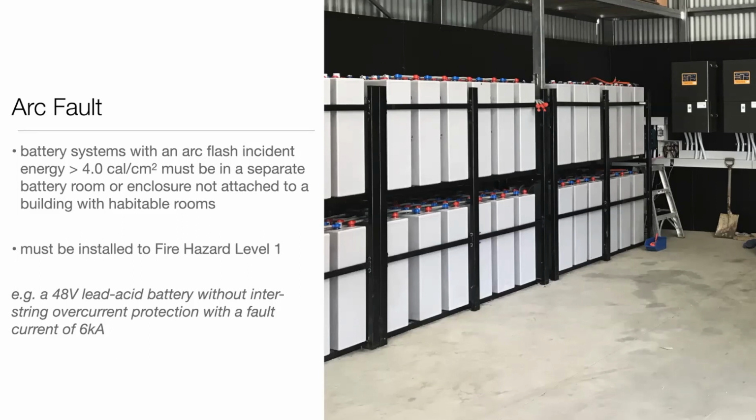Now, this was actually in a farm shed, so even though we did put string overcurrent protection in, so it would fall under 4 cal, it still could have been installed without that string overcurrent protection because of its location. And it must be installed to fire hazard level 1, which basically means it can't be within a building containing habitable rooms, and there are some other requirements with fire hazard level 1.